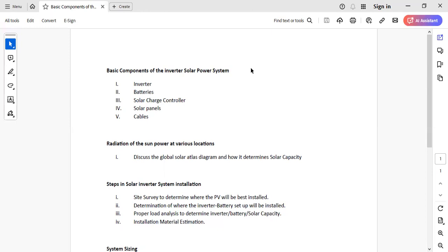Those types of battery he's talking about, I have even seen the one that is 2 volt 1000 Ah. I think we've used it on Huawei projects for telecom sites. Those batteries are used as hybrid batteries for telecom sites, where you see 2 volts 1000 ampere hour. They will be assembled into a 48-volt system, since in the telecom sector we use a 48-volt system to power our devices. At 1,000 ampere hour, when you multiply it, the kilowatt hour from such a setup will be very high. Those batteries are very good for backup.